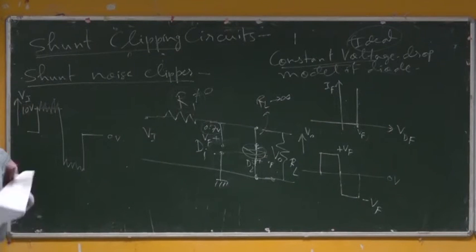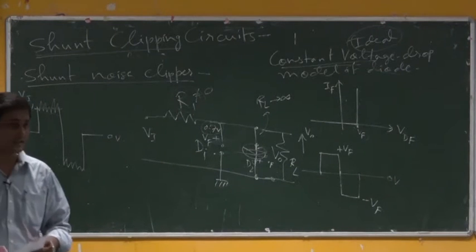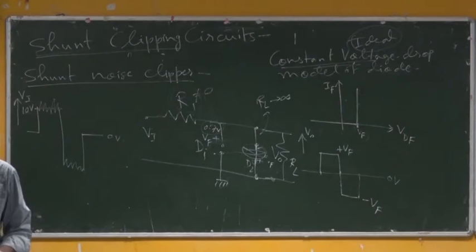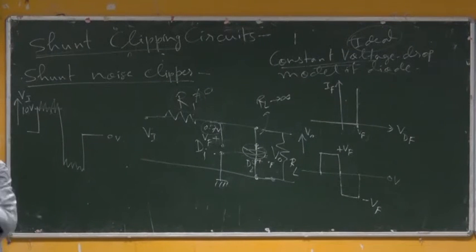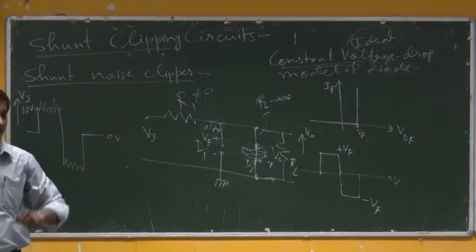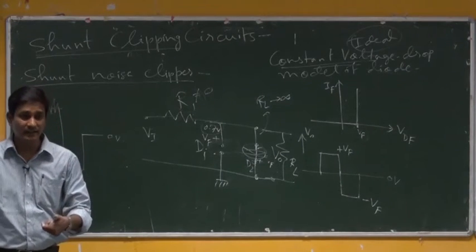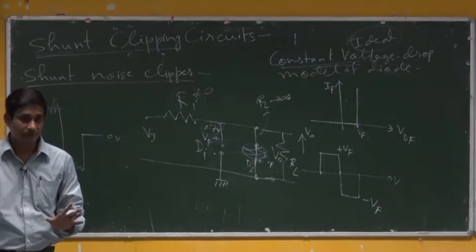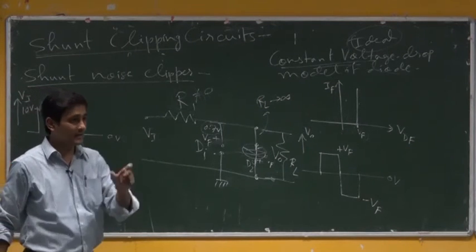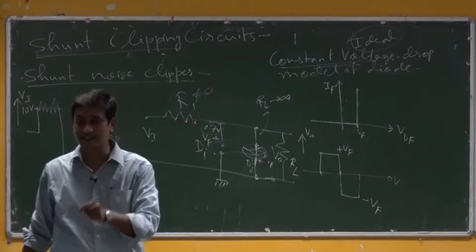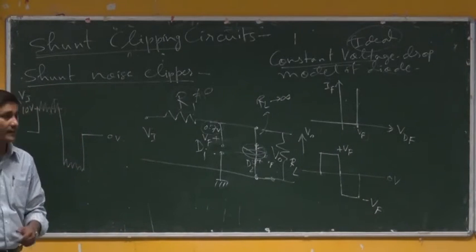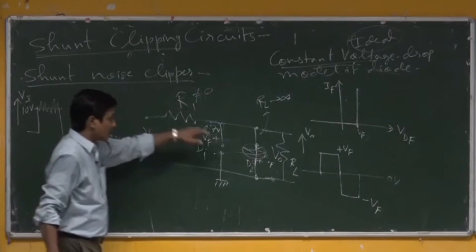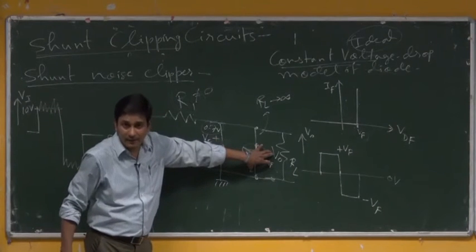If you have opened your small electrical circuits where LEDs are involved, LEDs are used for glowing, with one resistor and one battery connected there. If you directly connect the LED, it can burn any time. But if you see the actual circuitry where LEDs are used, you will see one series resistance is always connected to it. That series resistance is decided with respect to the current handling capability or power handling capability of the diode.